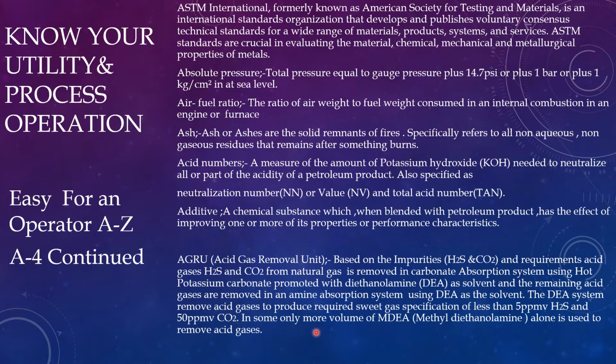In some cases, only DEA is used in large quantity, that is MDEA, methyl diethanolamine, is used for removing H2S and CO2. This is also used in the acid gas removal unit. This potassium carbonate and DEA can be regenerated in the regeneration tower. So AGRU plays a vital role in an LNG plant,